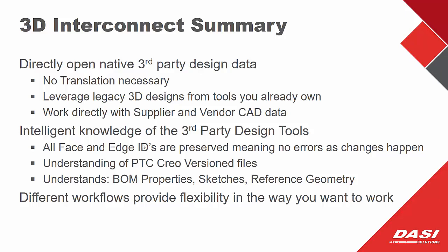3D Interconnect is also intelligent, understands when CAD data is changed within a native design system by honoring face and edge IDs, properties, sketches, and reference geometry. Changes to files are updated just like changes to native SOLIDWORKS files. File formats utilized by 3D Interconnect also open significantly faster than traditional export and import processes when CAD geometry has been changed in the native CAD system.